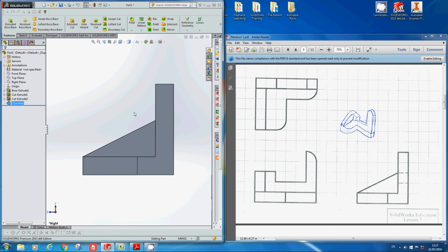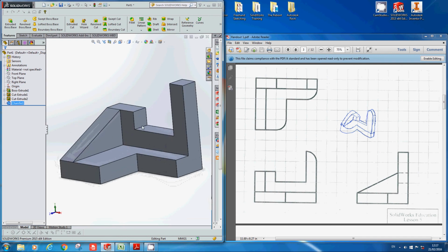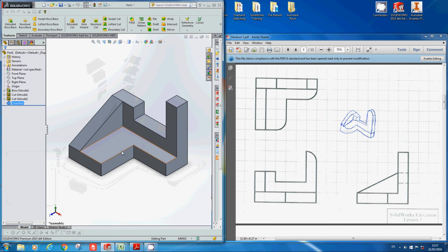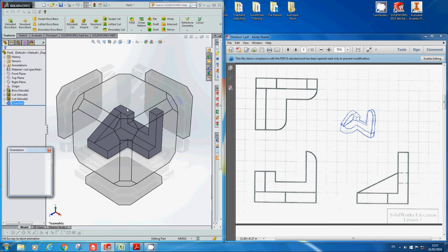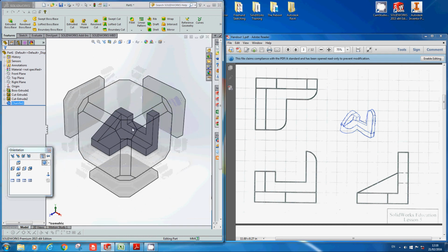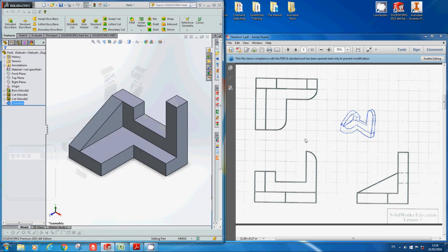So the last thing I need to do, I'm just going to rotate this slightly to this, and again if I hit spacebar I can put a more exact isometric view on it. And just a note, that's the cube active here. If you don't have it active, it won't come up. So I need to apply 3 fillets. I need a fillet here, and a fillet here.